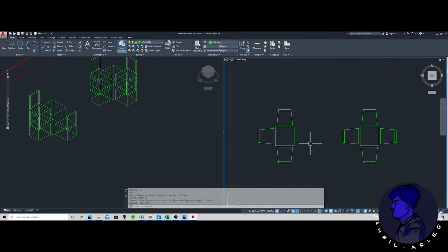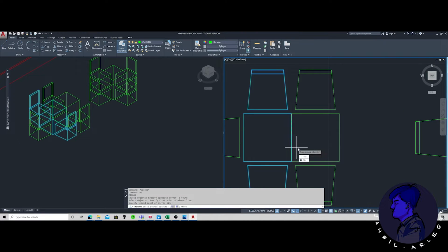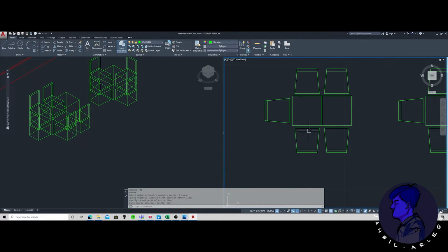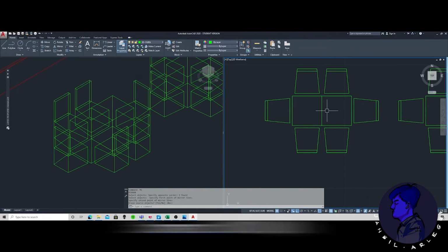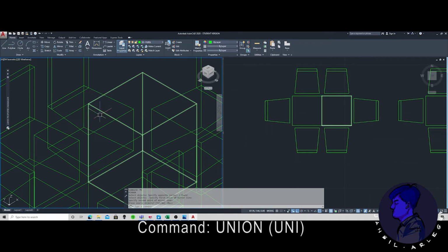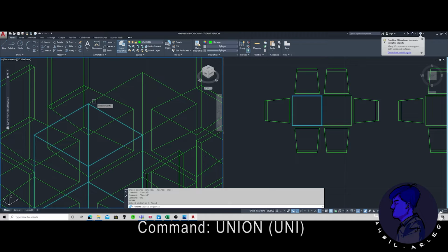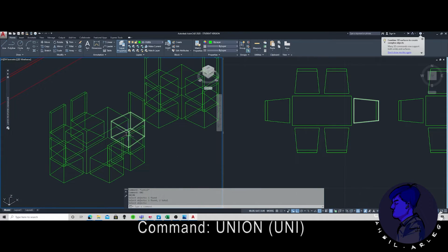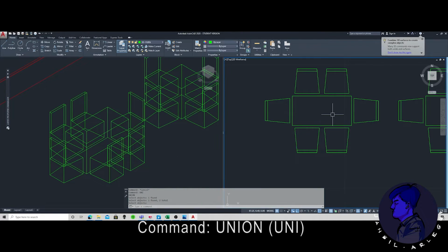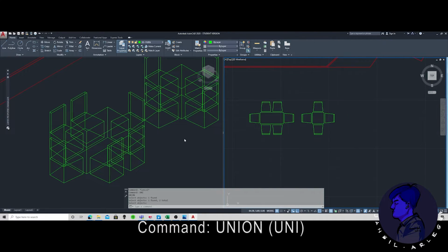So that 1.2 meters by 0.6 meter table version could be done like this. And then mirror, MI, this, and then you can union these two surfaces. UNI is the command for that. Unite, so there's no more line there. And I can start making iterations.